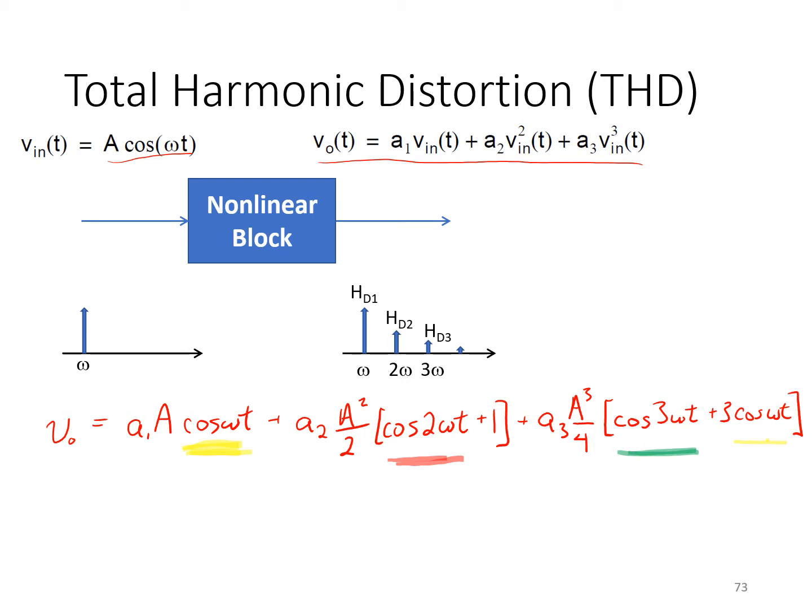So we'll sometimes refer to these terms as a first order term giving rise to the fundamental, the second order term giving rise to the second order harmonic, and the third order term giving rise to the third harmonic, HD1, HD2, and HD3, respectively.